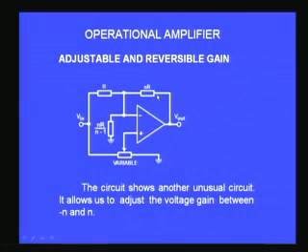If this is the case, then what will be the NR by n minus 1? N is 10, therefore 10 by 10 minus 1 is 10 by 9 times R. So, 10 by 9 is almost equal to 1, therefore I will make this also equal to 1k. So, I have 1k here, I will have 1k here, and I will have 10k here, and I have a potentiometer, it could be 1k or 5k, it does not matter.